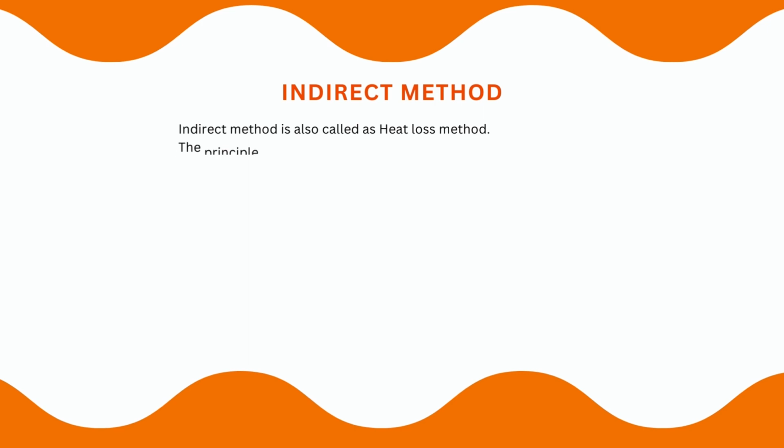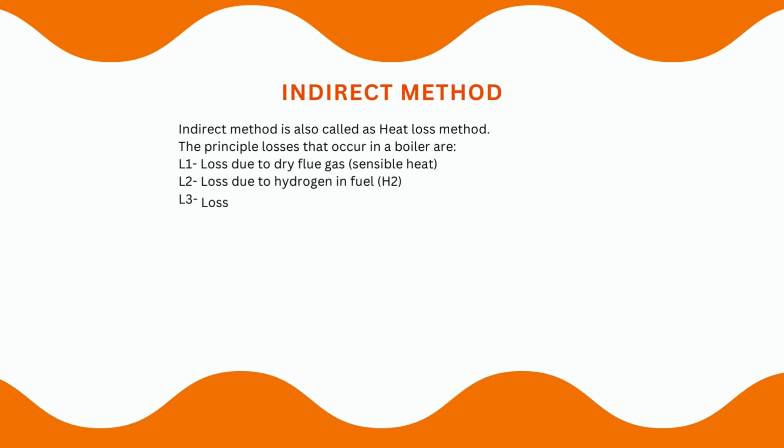Indirect method: the indirect method is also called the heat loss method. The efficiency can be arrived at by subtracting the heat loss fractions from 100.